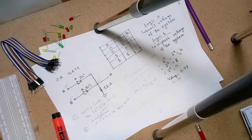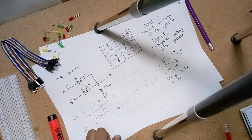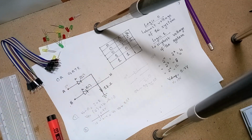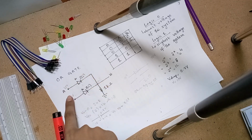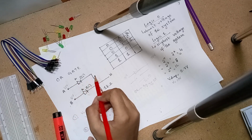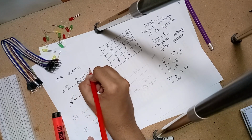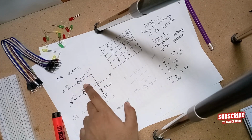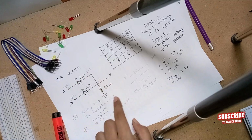Now similarly in the third case, we are also going to get a 1. We're going to provide 0 volts at point B and 10 volts at point A, and in this case diode 2 will be switched off and diode 1 will be on and forward biased. Again we are going to get a drop of 0.7 because it is a silicon diode, and we can subtract 0.7 from 10 volts, and again we are going to get 9.3 volts.